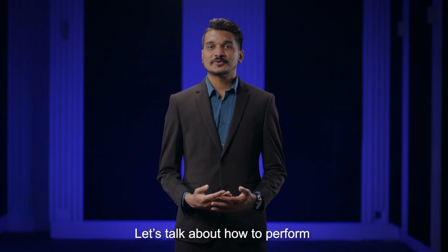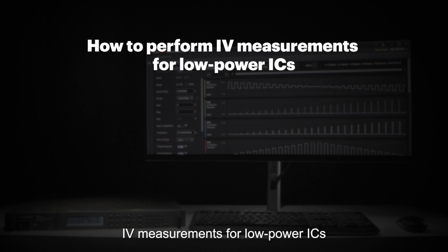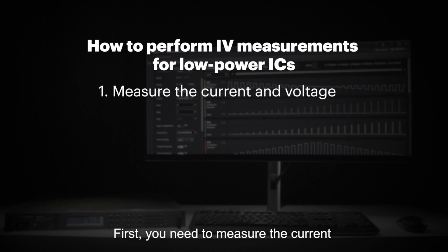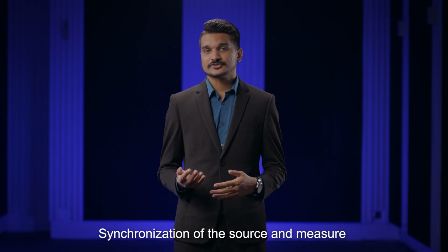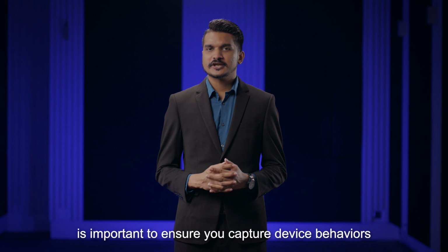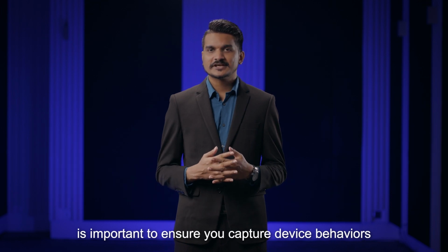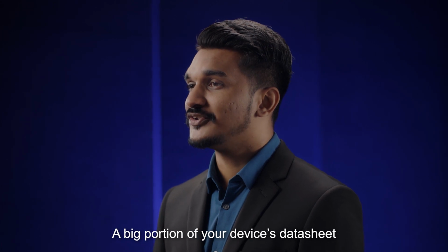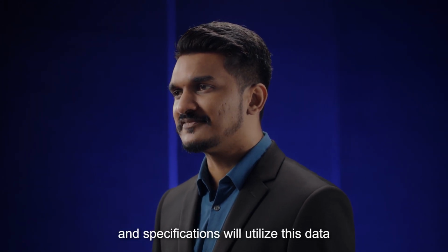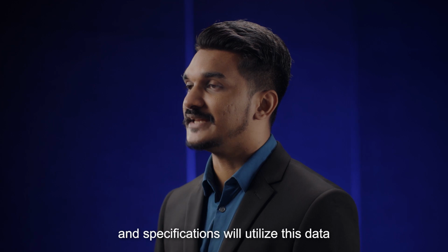Let's talk about how to perform IV measurements for low power ICs. First, you need to measure the current while sourcing the voltage at the same time to draw the IV curve. Synchronization of the source and measure is important to ensure you capture device behaviors according to the specific changes in input. A big portion of your device's datasheet and specifications will utilize this data.